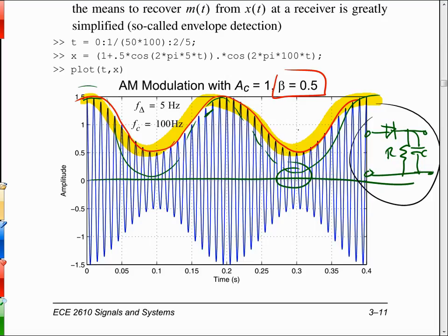and then just have this long wire strung out on the floor, and a simple tuning element would be out in here, an inductor and another capacitor. So this would be a tunable capacitor, and you'd put an antenna on this, and you can build an AM receiver with just those parts right there. No one's ever done that before? You haven't lived yet. You need to go to Radio Shack and buy one of those experimenter kits for probably less than $10.